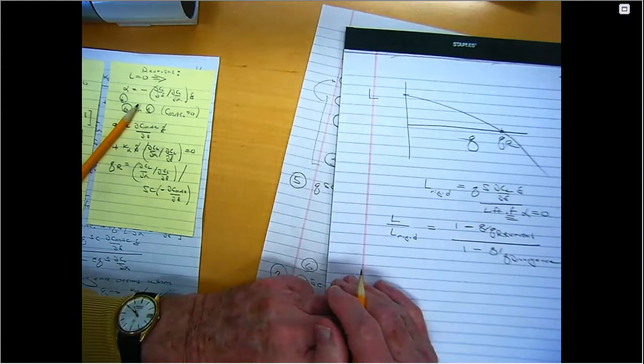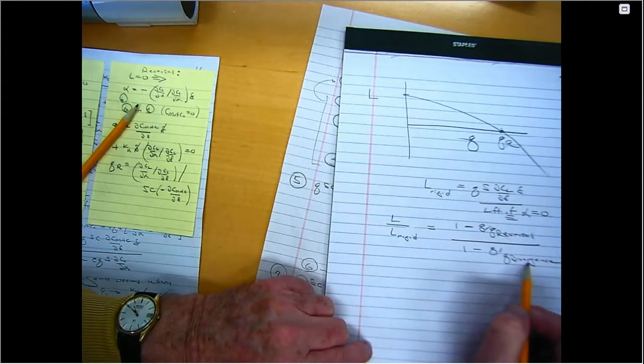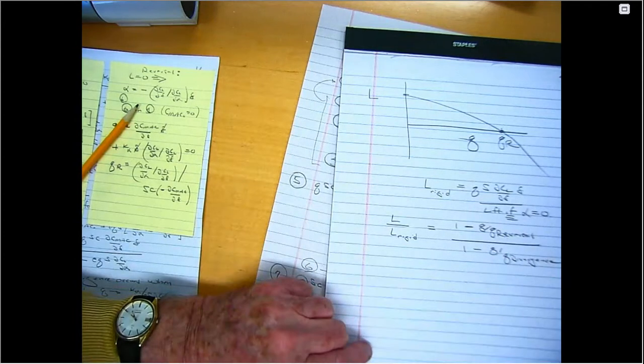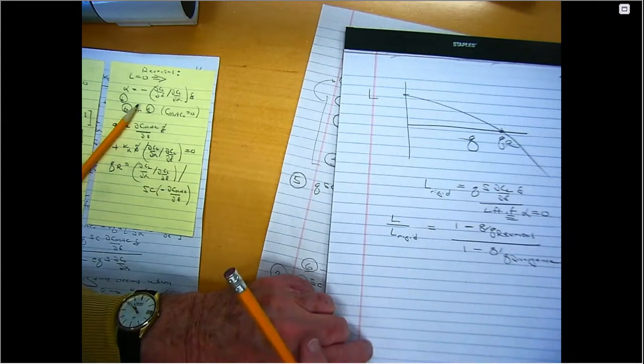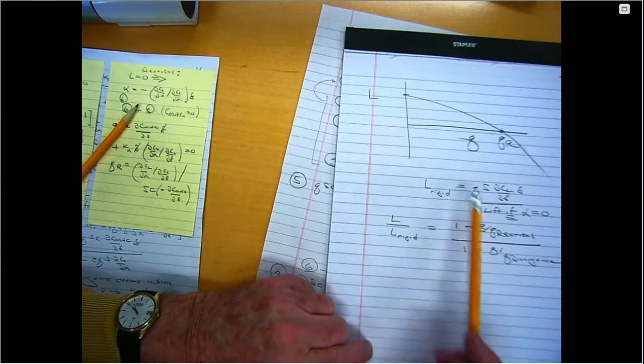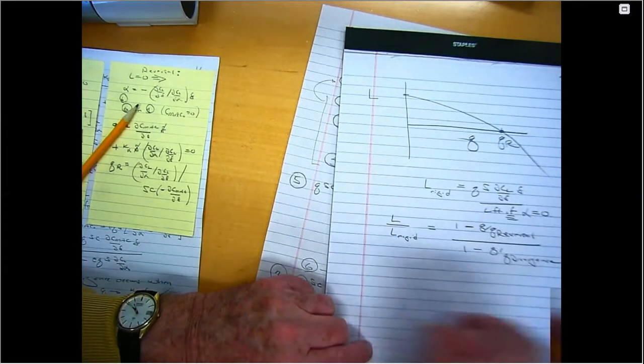That's neat, right? But remember, buried in Q reversal and Q divergence are always parameters. K alpha is in there, E is in there, C is in there, S is in there. All those aerodynamic coefficients are in there, right? But nevertheless, if you define Q reversal and Q divergence, this is what? Which is neat. And so this curve is just a plot of this formula, right?